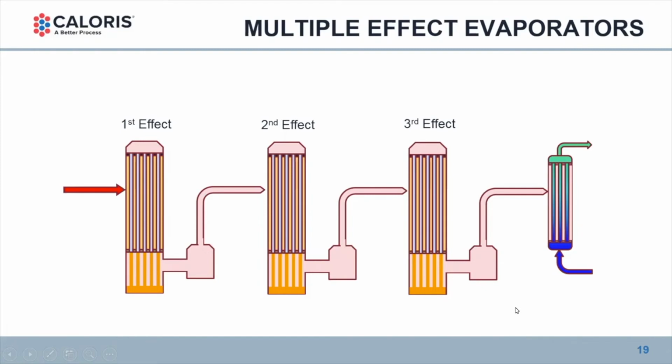If we are on a single effect evaporator, particularly MVR evaporators, where what we evaporate is being compressed and creating the steam that goes into the shell of our evaporator, then we usually need to add a separate degassing step for the feed before the feed gets into the evaporator. Because otherwise, that non-condensable gas really begins to bite quickly and cause problems.